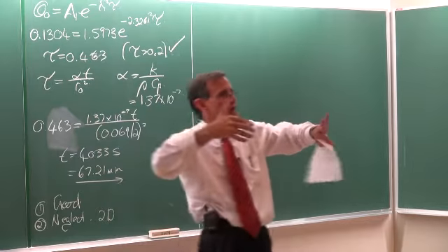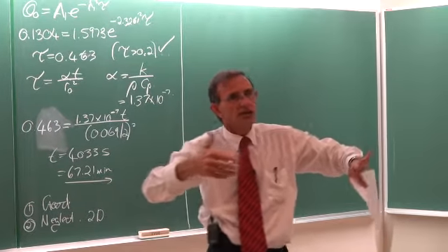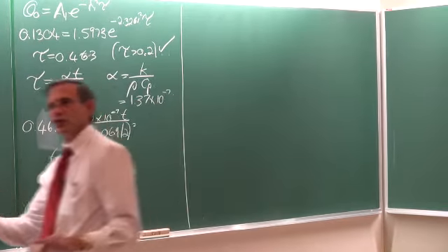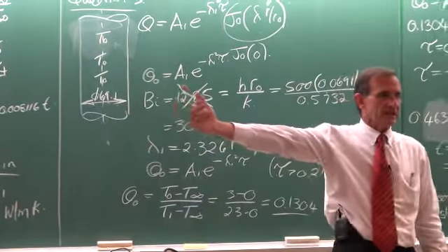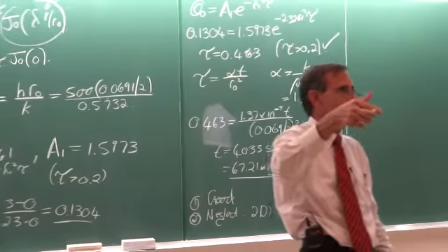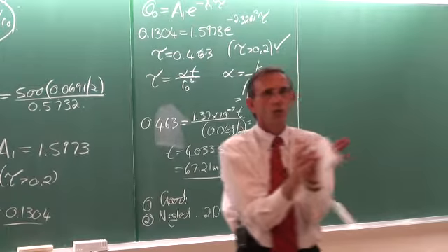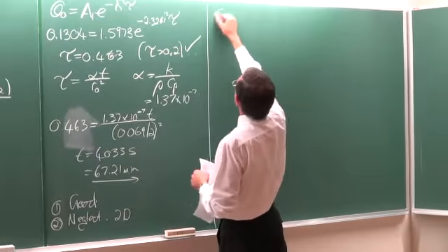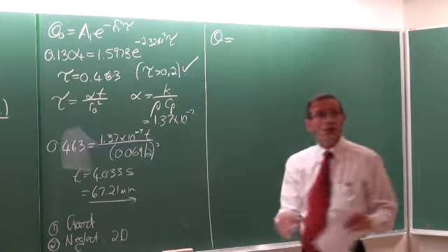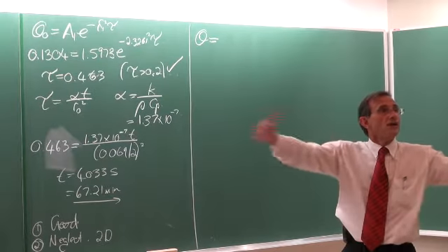Right. The next one is to consider it as a semi-infinite solid, and we have to solve it now. There are 4 cases in the textbook that we've looked at in terms of boundary conditions. For this one it's very clear: the heat transfer coefficient is given. It's not a laser, and the temperature on the wall is not given. So case 3 gives the non-dimensionalized temperature, and it is a long equation.